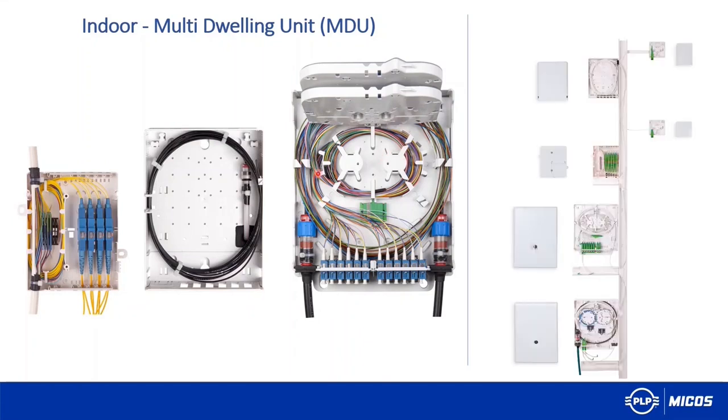And here you can see how it actually looks inside the apartment building. So we set a basement box. On the first floor, you can still have the same box, but you can swap it to a different size. And basically, if I talk about the capacities, I can fit here 48 LC connectors or 96 or 72 splices. For the second box, I can do half capacity, it means 24, and here I can do 12. So 12, 24, 48 in case of connectors, and then splices 12, 24, 48 or 72.